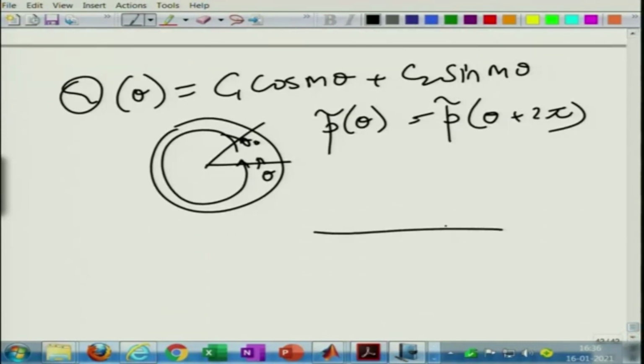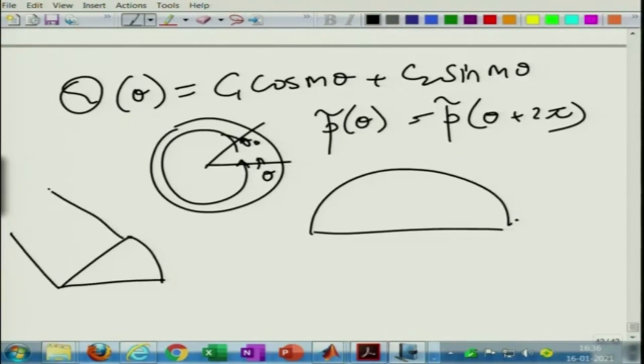There are actually cases when you have a semicircular duct, a semicircular muffler, or problems in applied physics and applied maths, where you have wave propagation in a pi kind of sector, or a vibrating diaphragm of a pi kind of shape. Then of course, you need to worry about rigid velocity boundary conditions at theta equal to 0 and theta equal to theta naught. Then m need not be an integer.